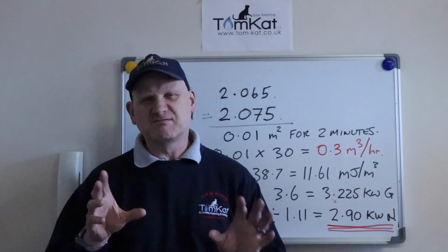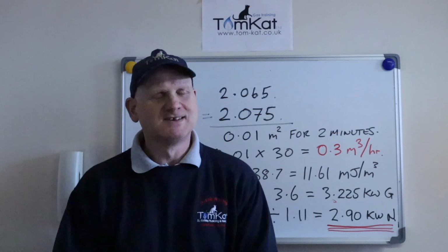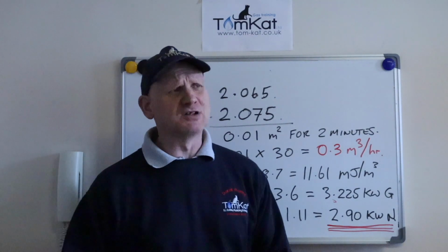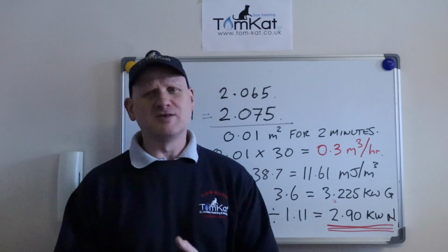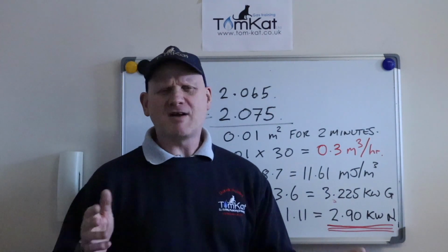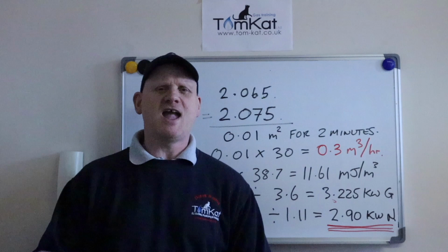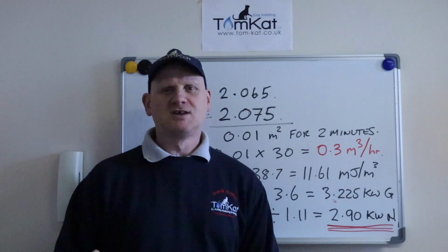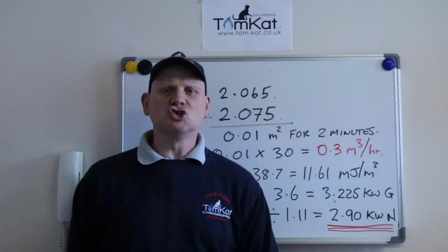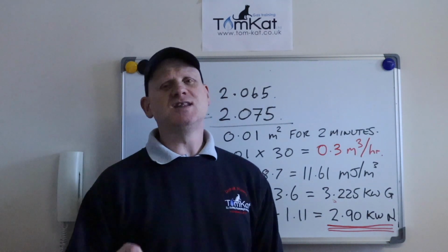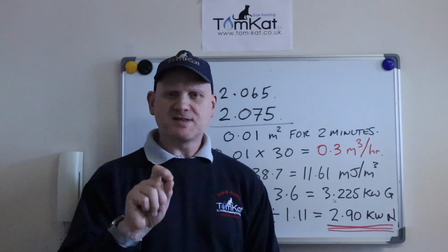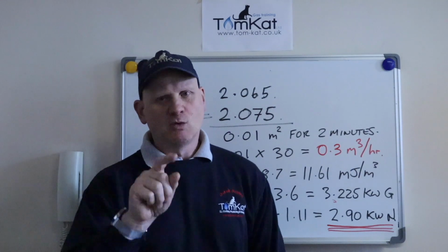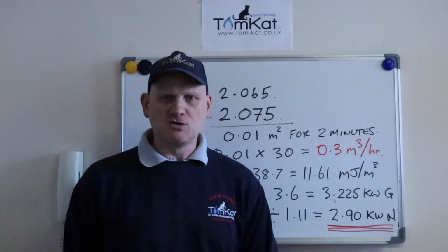Okay, now another bit of contention in the gas industry is how much do we allow? Now you'll hear some people will say it's 5% under, it's 10% over, but there actually isn't a figure given in any books, any regulations, because it goes off the engineer's judgment. Now gas rating is only a small percentage in the regulation 26.9 on checking whether a gas appliance is safe to use or not.